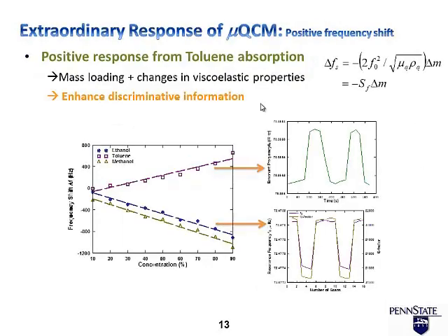And during the experiment, we observed two very interesting responses of our sensing system. According to the Sauerbrey equation, which is a very famous equation, we expect that the frequency is going to decrease with addition of the gas molecules due to the absorption of mass.